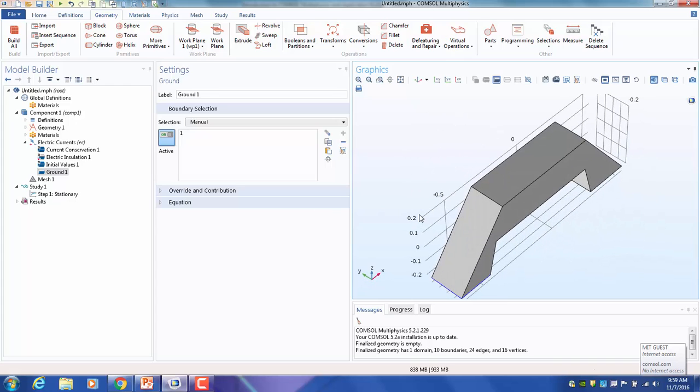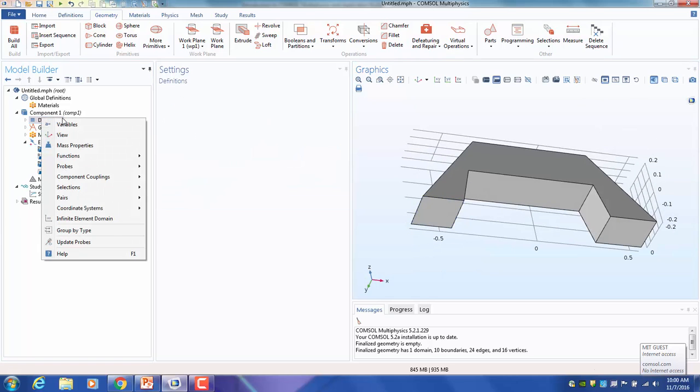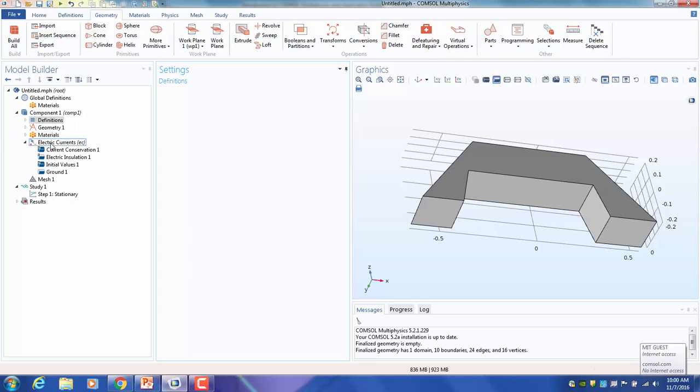If there is a very complicated geometry where some surfaces are hidden inside the domain, you could use the transparency option or the wire rendering for a different visualization. And you can hover your mouse over and then use the center scroll wheel to cycle through the different surfaces, the different layers of the geometry, to get to the inside layers. So again, that makes the selection easy. You can also, in the definitions, define some selection list, like everything within a certain ball shape belongs to one group,